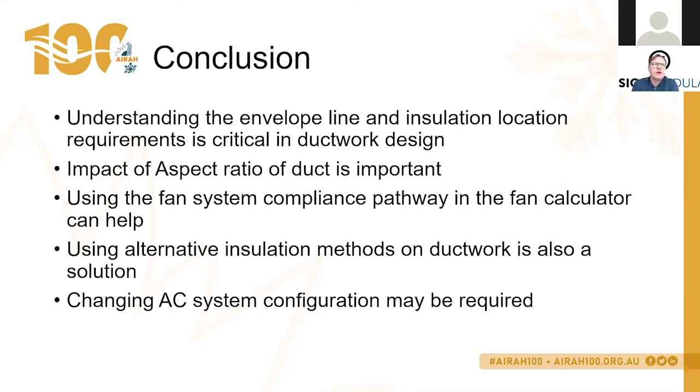So you find that the temperature in that riser would stay very stable, and we could realistically consider that it probably is part of the conditioned space. So no, it doesn't necessarily have to be outside. It could be within the conditioned space. But you need to discuss that with the builder and how the builder is building the riser.